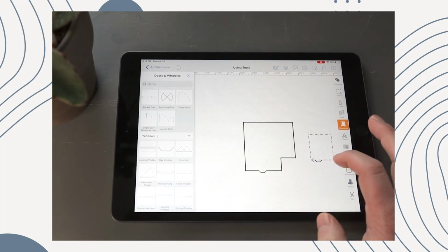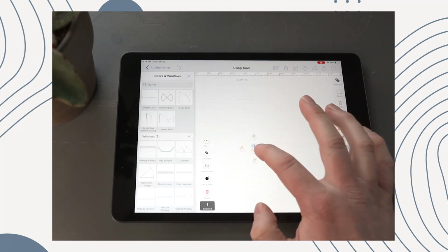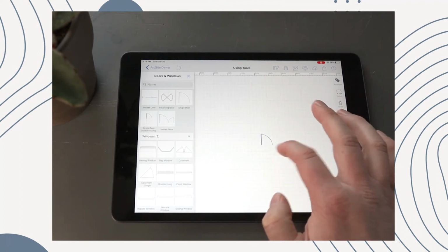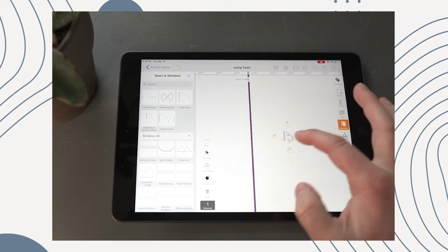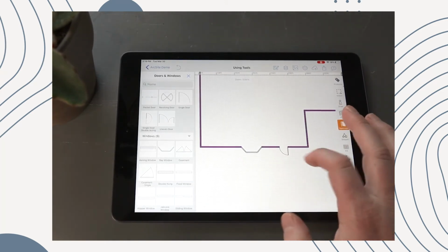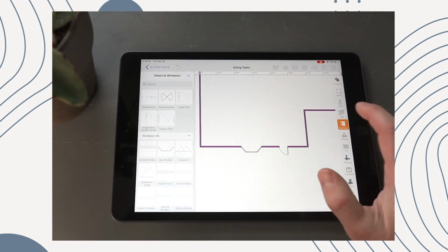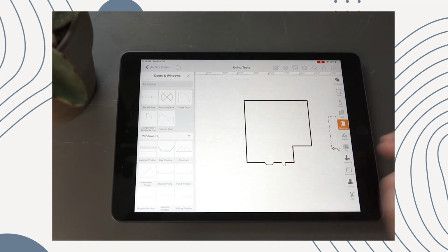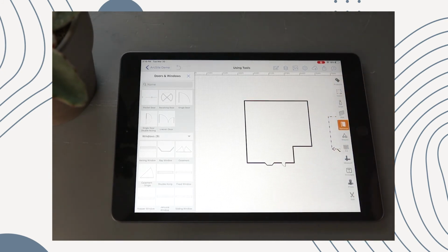That's when you use just the draw tool, but when you use the openings tool, and let's grab a door too to demonstrate this a little further, all those 14-foot doors that you're used to seeing, see how the openings and the walls play together. So if you're doing a floor plan, I recommend doing it in the wall. And then if you're adding text or marking it up, marking different diagrams or electrical routing or whatever it might be, that's where the draw tool would come in over the wall tool.